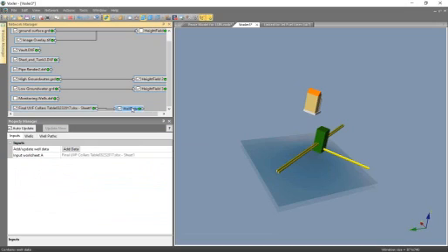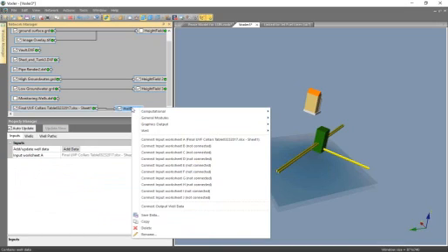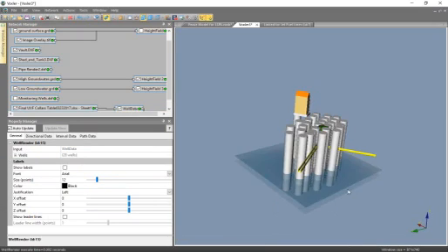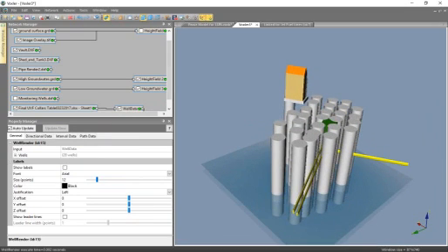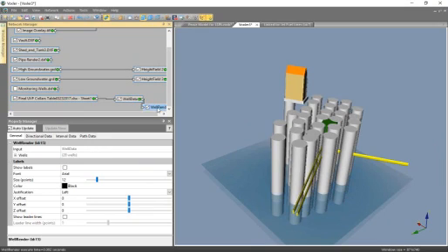You see our well data module, and again I can right click here, go to graphics output and well render, and then we can see the boring locations here inside of Steve's project. Now, of course, these boring diameters look a little bit too big, so let's go ahead and change that.